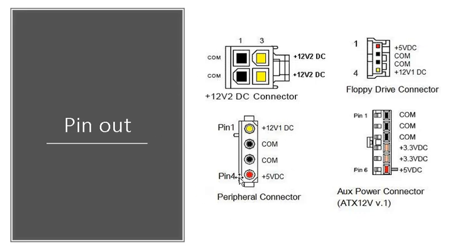The pinout pretty much says how much voltage each one of these pins gives out and which ones are common. So these are your commons, these are your grounds, and then you have the 5-volt DC that comes out from pin 4, and you have 12-volt DC that comes out from pin 1.